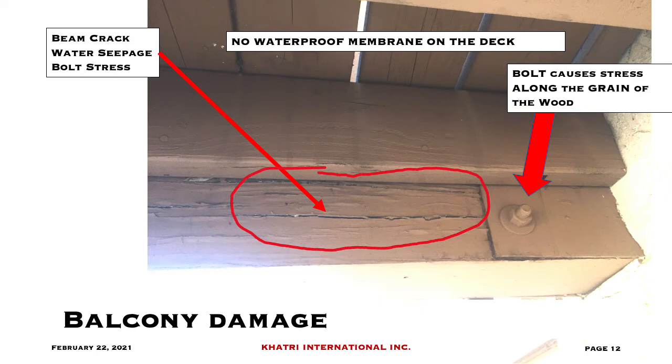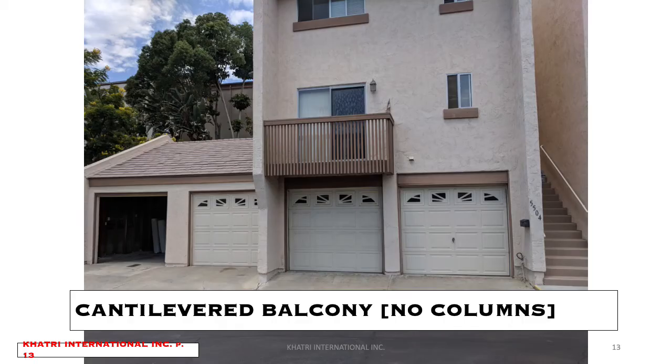So every time it rains, or if this person were to have potted plants or any type of vegetation, they're literally destroying the balcony that they're living on. And so a lot of the causes are coming from the unit owner themselves. A lot of the distress comes from them, because California doesn't really get a lot of rain. Most of the water is coming from the occupants, from their own irrigation. So in this case, this shows you a cantilevered balcony with no columns. In this particular project, which is in San Diego, all of these balconies are being replaced.